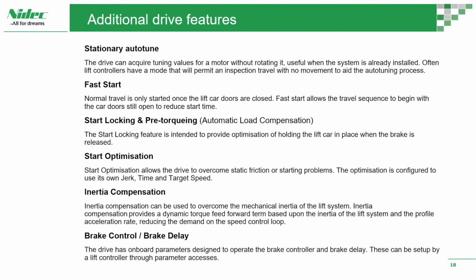Fast start. So for normal operation that is not using fast start, the actual travel is only started when the lift car doors are closed. With fast start, basically this sequence gets sped up so that the travel sequence can actually begin while the lift car doors are still open or in the process of closing, to reduce the start time and improve the flow of traffic within the building.